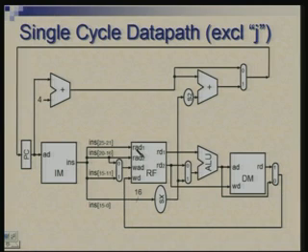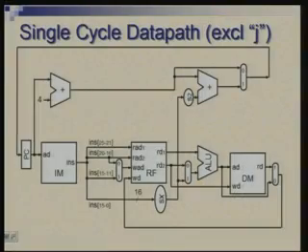Here, step by step, we did two or three things. One thing was that we tried to economize on the resources, and wherever it was possible to merge, we did that. Then we introduced registers to make sure that resources become free for the next operation after one cycle. Registers are actually there to store the value, so that the resource becomes free.